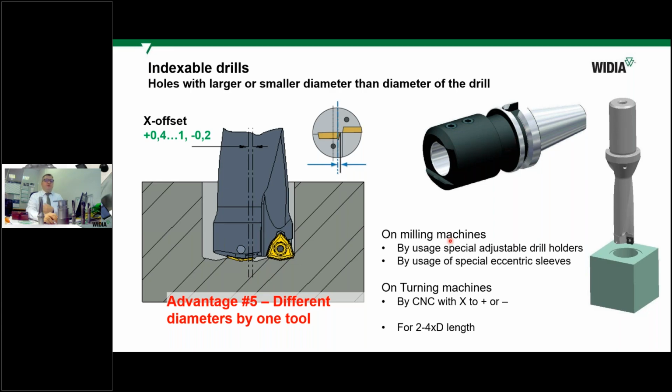For sure, in general, the recommendation is to decrease the feed on the entrance at first. And for sure, in unstable elements. So, for example, cross-hole drilling. So, when you cross the hole, when you drill, it is about 30% to 2 times better to decrease the feed. Because this webinar is dedicated not only to our drill named Top Cut 4, but basically about all indexable drills.